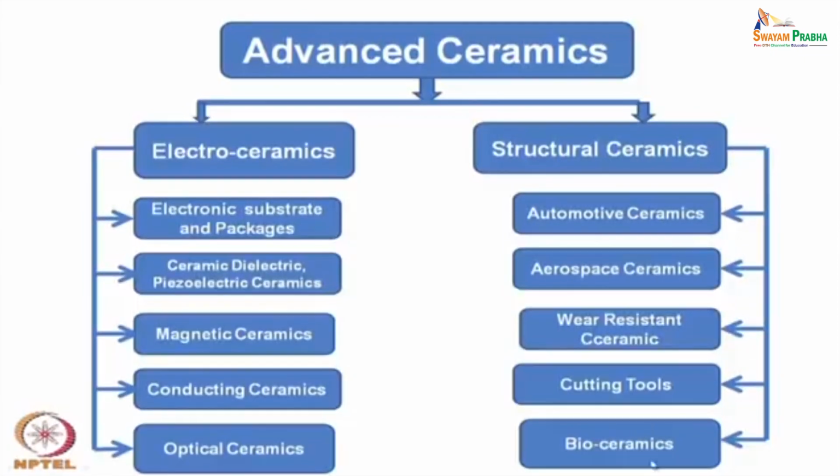In addition, there are many other ceramics which can also be used for biomedical purposes. That group of ceramics not only uses the mechanical properties, high strength, high hardness and abrasion resistance of the materials, but also needs different kinds of chemical inertness, as well as sometimes reactivity with the body fluid. Ceramics are inert so far as the body fluid is concerned, and therefore a group of ceramics has come up in very recent years as bioceramics.